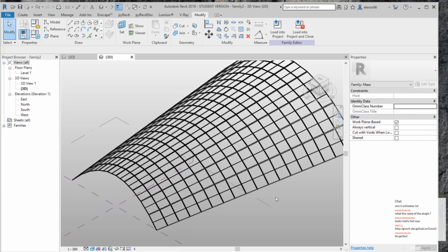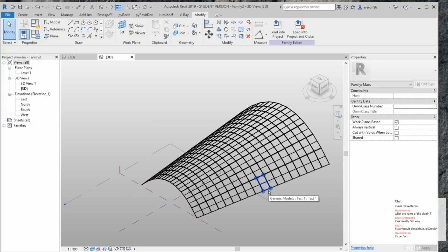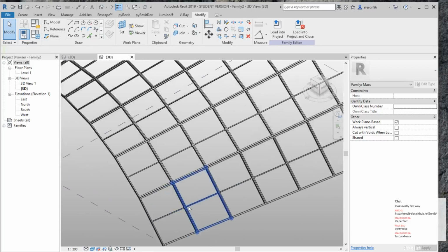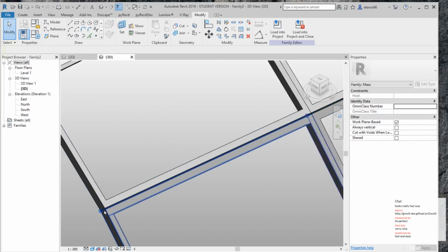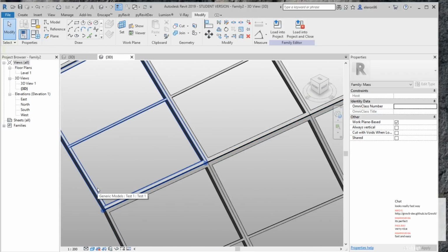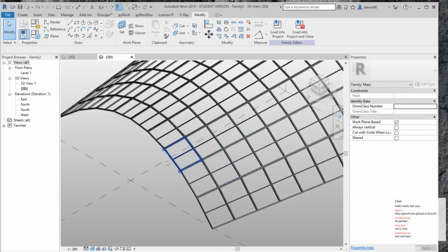You can create whenever you want. You can create what you want here in Rhino, and after that you can send it to the Revit. If you understand how the adaptive family works, as you can see, here is my adaptive family. It's laying really perfectly. If you understand how an adaptive family works, you don't need to use Dynamo, you don't need to use any parameters in Revit. You just need to create it and spend time on the adaptive family. Once you create an adaptive family, it will always work with Rhino and Revit, and this is a really cool feature.